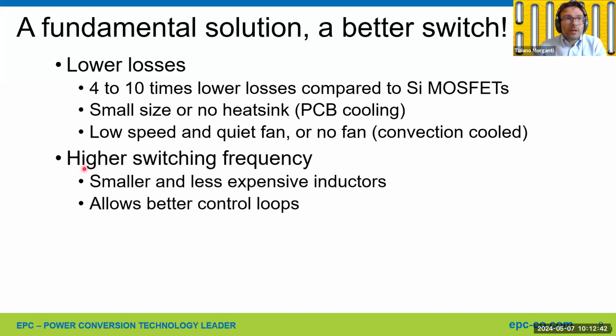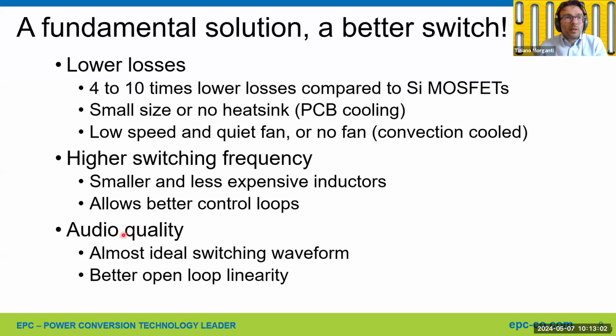Also, we can offer higher switching frequency. This translates into smaller and less expensive inductors for the output filter, and also the opportunity to implement a better control loop to achieve better audio performance. In terms of audio quality, our devices are switching very fast, and they offer pretty much ideal switching waveforms.